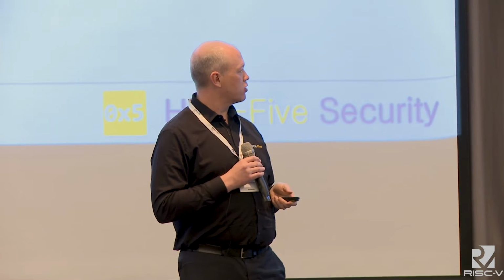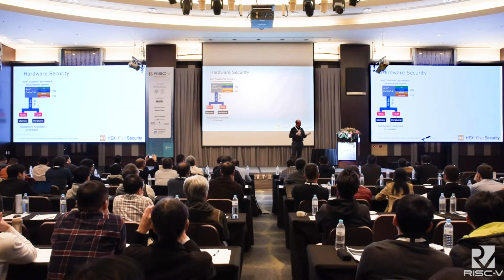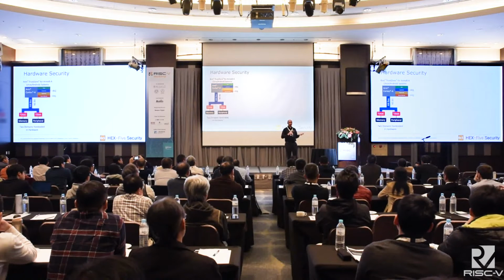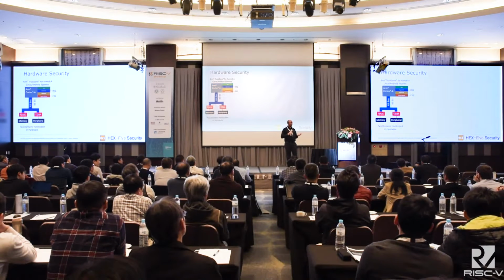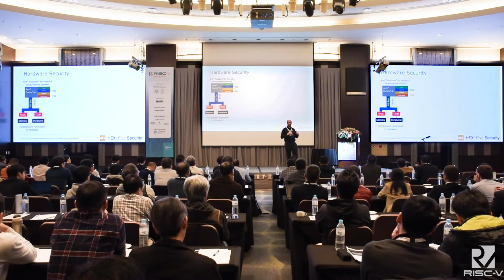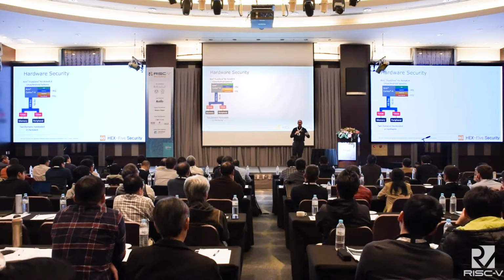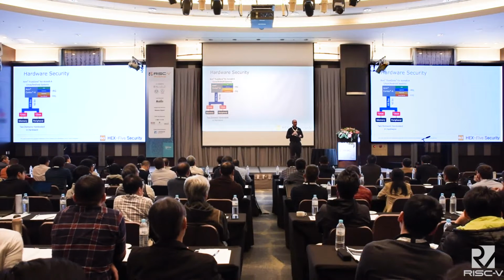It's also pretty difficult when that starts to be multiple cores across the same bus to manage all of that structure. The second problem is when you trigger one of these exceptions. So if you try to do something that you're not supposed to do, you don't get a real-time exception back from these downstream peripherals. You get an exception that happens much, much later. So it's very difficult for you to trap that and do something useful with that information. You end up sort of blocking that and then having to go back and recover from quite a long structure.